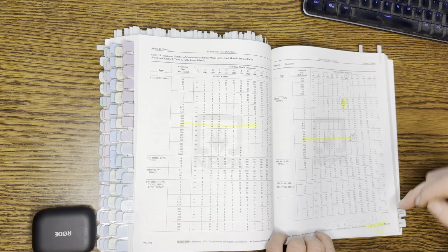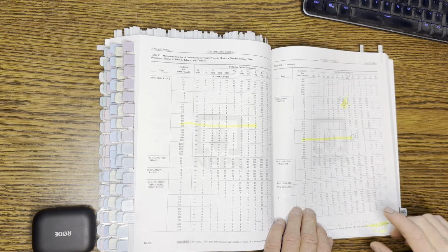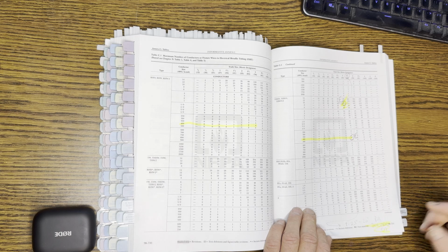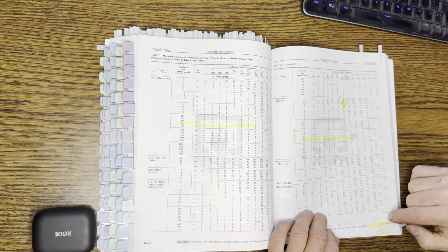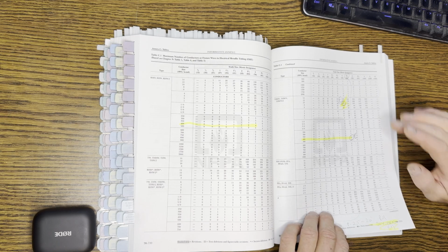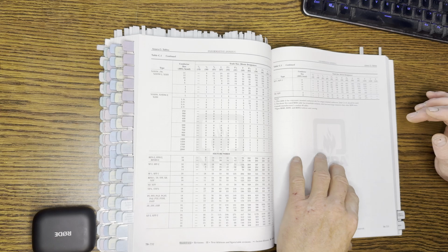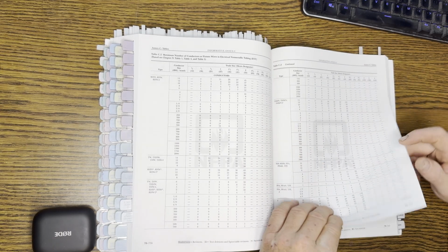Just go back. When you look at these tables in terms of what size you need and how long of an extension you need for pull, it has to do with whether you're pulling straight through, etc. Just look at section 314.28(A)(1). So I have some references here that'll help correlate these tables to reality.